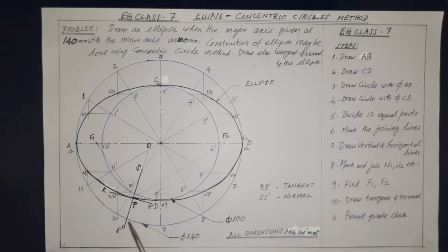Here, if the bisecting method procedure is required, please refer to EG class 3 that I have already given, where arc bisecting procedure is explained. A similar method is used for this angle bisection also, or otherwise a protractor may also be used to get the bisecting angle, but ensure no mistake is made to bisect the angle.